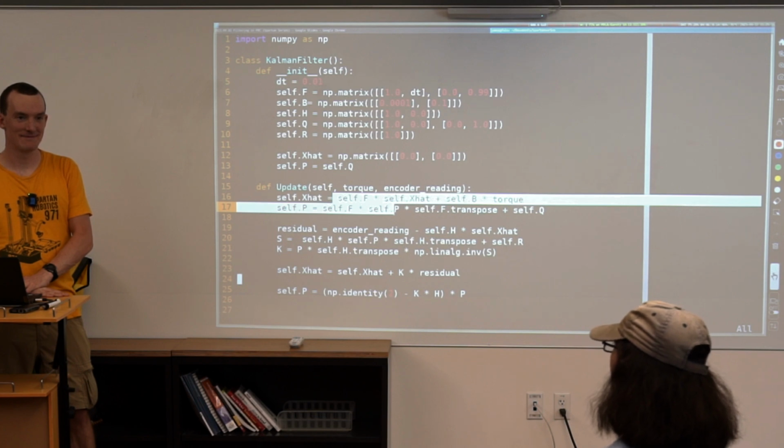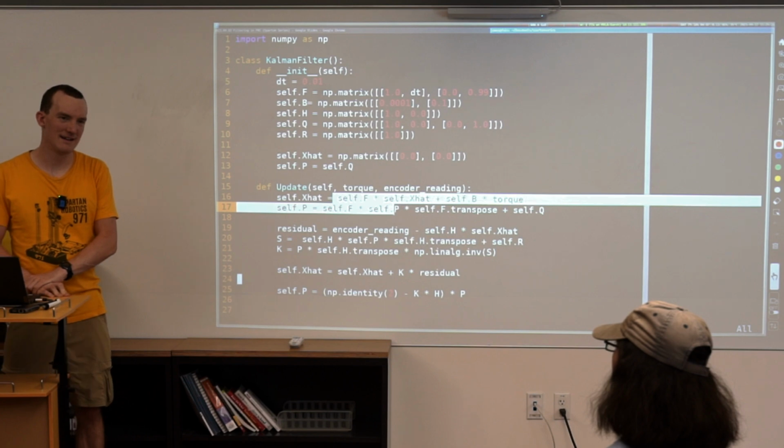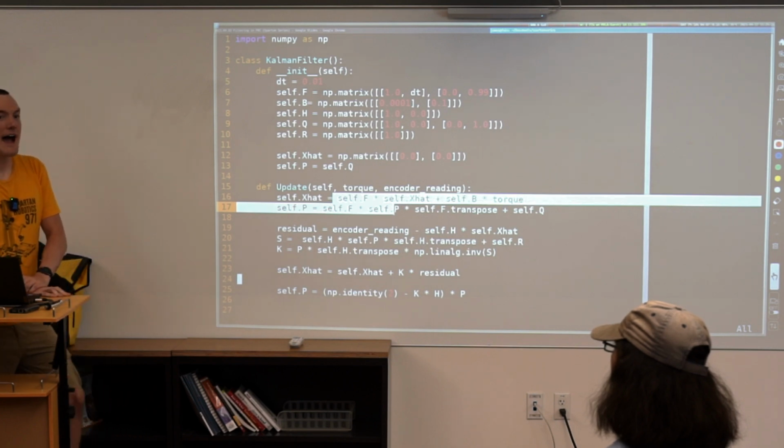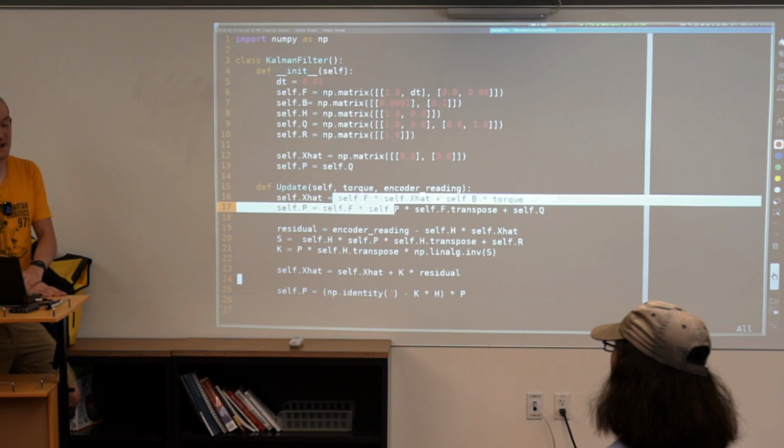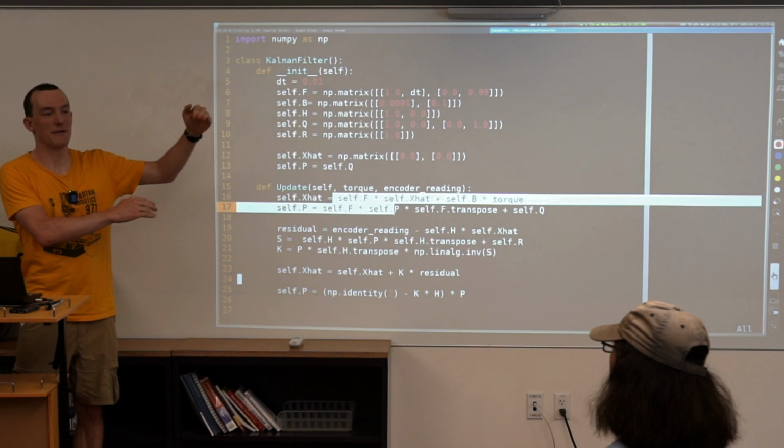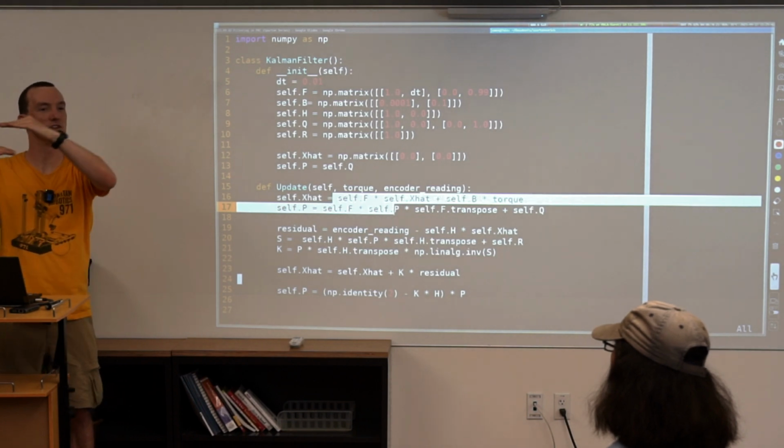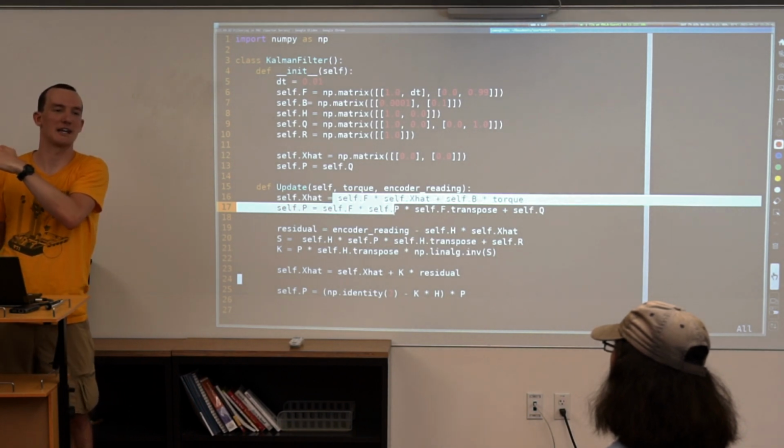I imagine you do similar things, like just measuring noise on a sensor. Yeah. That's one of, like you said earlier, kind of a hard one to get. Yeah, and the problem is if you just look at a sensor and measure noise on that alone, that may not actually be what you care about. Like you may get issues with the backlash on the mechanism, which means that you fundamentally can't trust it as much as just if you take all the numbers. If you take the sensor and just take the standard deviation of a bunch of numbers, that may not be what you actually care about for the noise.